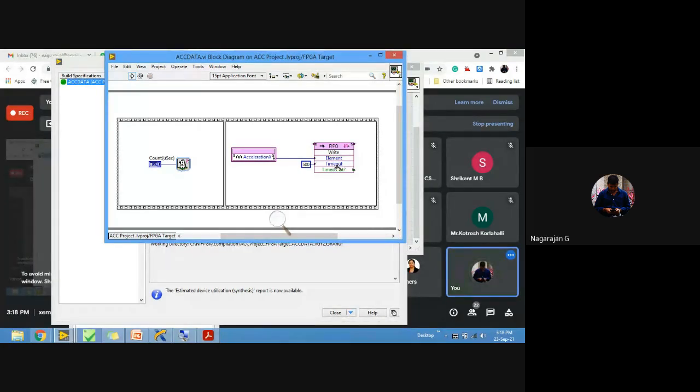This timeout specifies the number of clock ticks the FIFO function has to wait for available space in the FIFO, in case the FIFO is full. A value of -1 prevents the function from timing out, and a value of 0 indicates there is no wait. It is going to write a constant of 0 to timeout if we use the FIFO method node in a single-cycle timed loop.